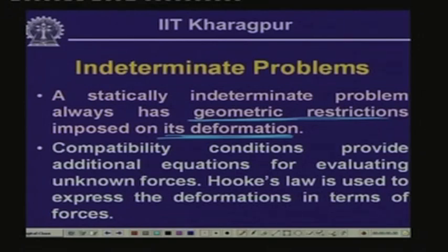So, compatibility conditions provide additional equations for evaluating unknown forces, and thereafter we can adopt Hooke's law to express the deformation in terms of forces. We first write down the compatibility criteria based on the deformation, and then we adopt Hooke's law to relate the deformation to the forces, and finally we get equations from these compatibility criteria which help us to solve the unknown reactive forces.